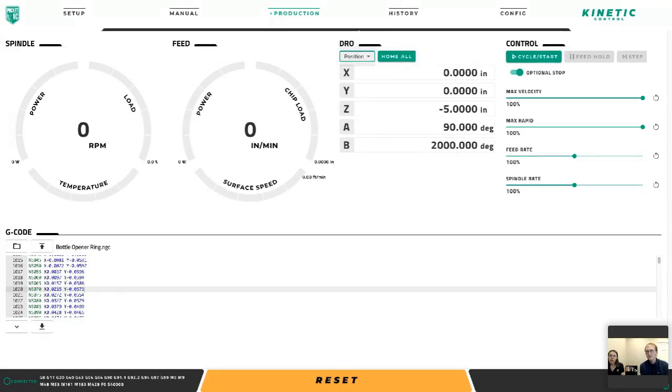Can you maintain a constant feed rate at tooltip? That was the second question. Yeah, I mean, that's pretty standard. So you can set your feed rate. That's determined by your post processor. So yeah, it's up to the post processor to properly get your feed rate correct.